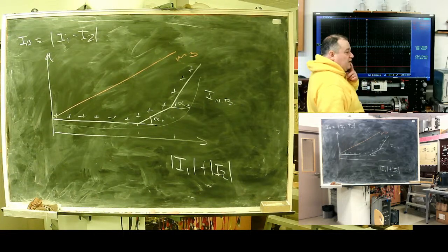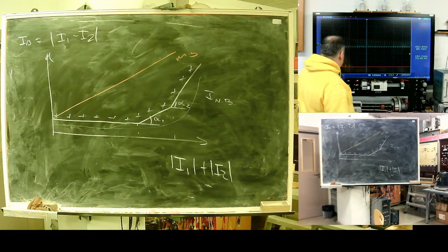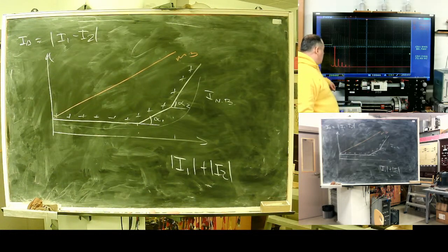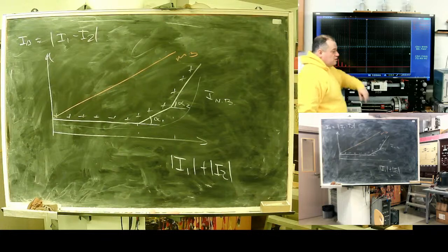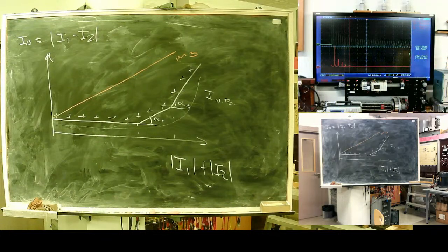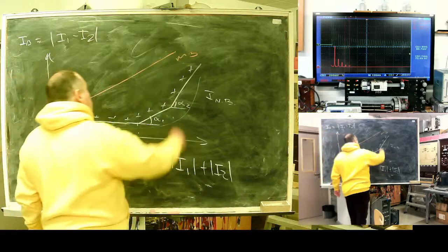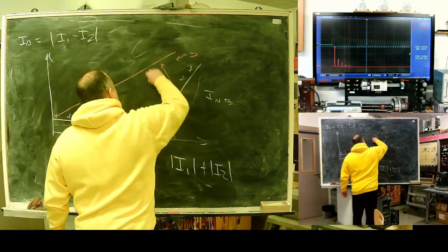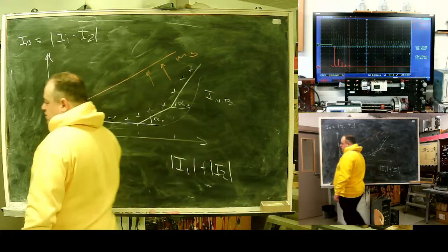Why not odd harmonics? In case of current sensor saturation, there will be odd harmonics. Sometimes the 200 Hz component is also used. It can be done, but these two are the most usable. So presence of high harmonics tells the relay to shift to the restricted operation characteristic.